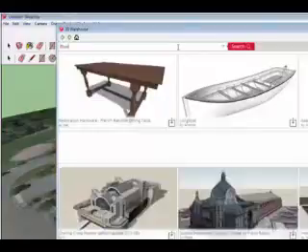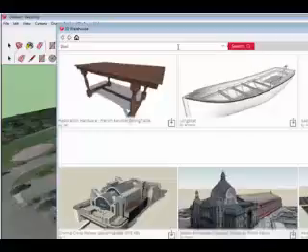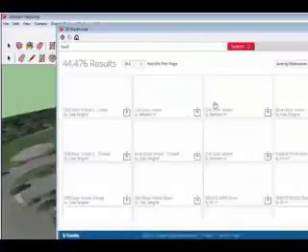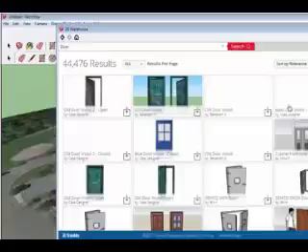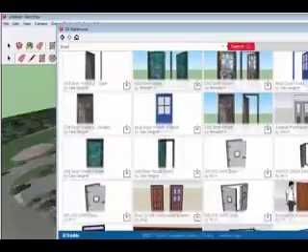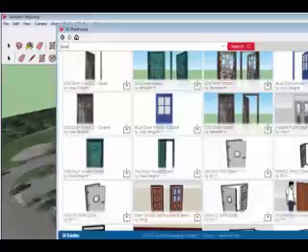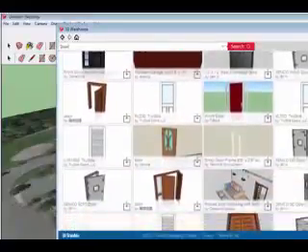So you can say, okay, I want the doors. Now, they won't have the ability to be as detailed, but the way I use 3D Warehouse with them is they can go take the doors and set them in on the object they want. So we're going to do a search for doors, and it can be anything, and then they can look and find a door that is close to what they have. So let's say we had a front door, a 3-panel front door like this, or we can have more of a school type door.